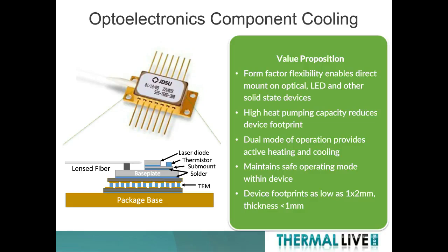Yeah, so they are widely used in datacom and telecom, and the main benefit they bring is the control of the emission wavelength of the laser. The laser wavelength will vary with temperature, and having a thermoelectric cooler allows you to control the temperature of the laser and thereby control the wavelength. This is very useful for DWDM applications, where even a little bit of drift in wavelength cannot be tolerated.